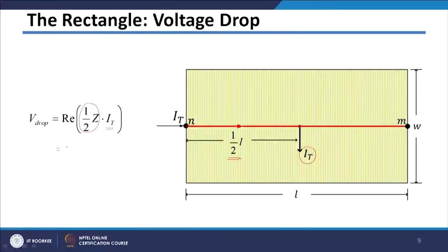Let us see, if you want to lump this load at the end. In that case I can just take this half related to IT. So this same equation will become like this, and from this, if I take the total impedance into account, half of the current should be lumped at the end. In that case your model will be something like this. You can lump at the end, the total impedance will come here, and the current value, or total load value, will be IT by 2.